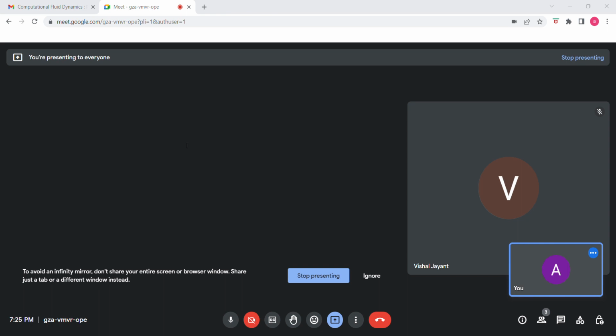Which of the following is an admissible extension of equation 1 to steady heat conduction in 2 dimensions? We know the equation is q is equal to k d square t by dx square, which can be extended to 2 dimensions: dou square t by dou x square plus dou square t by dou y square is equal to q, where q is constant. Here option 1 is not feasible because it becomes non-linear with respect to x only. This is not a direct extension of equation 1. In the same way, the other option is an unsteady state problem, which is also not true. So option 2 is the only correct answer.